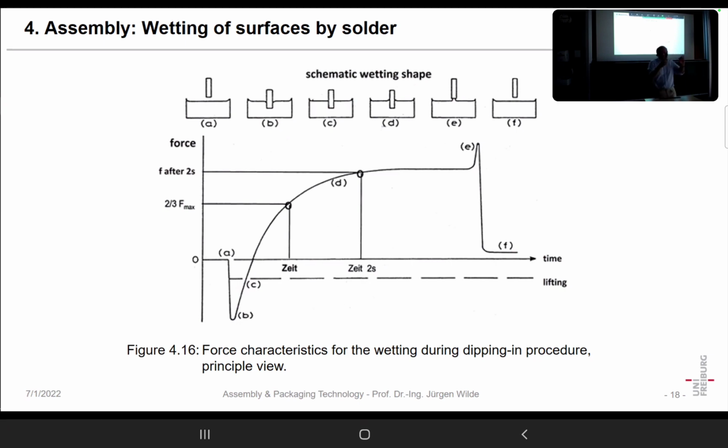And when we take the time constant using that exponential curve, it's always 63 and a little percent, and that's roughly 2/3. So maybe for some people who didn't study or so, but who have to evaluate such curves, 2/3 is easier than to take something from an exponential curve. And so you could say that's quite a good estimation of the time constant of that process.